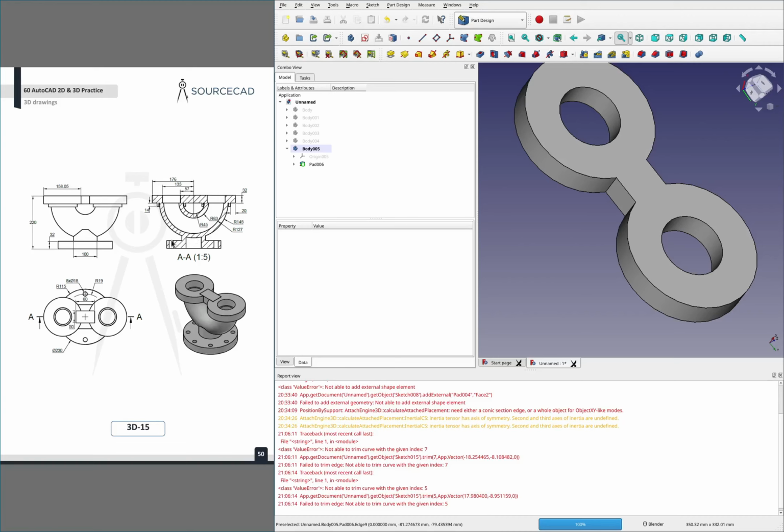I'm going to do this section here next, and then I'll do this bit here, where it comes up and joins with the rest of it. The reason I'll do that is because then I can just extrude it up here some amount, and when I come through with this sweeping extrude and cut, it'll clean that up.